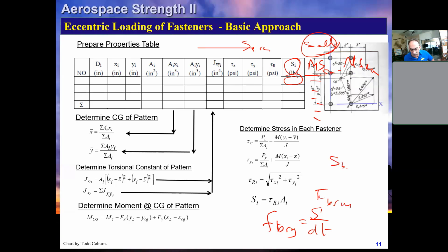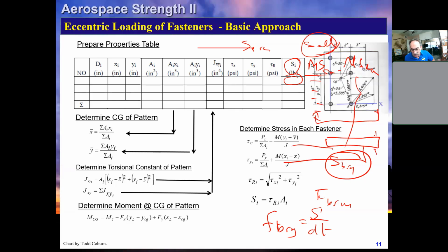If we have an S bearing of the fastener, then we can just write the margin of safety directly. If we need to calculate bolt bending, we look at the cross section of this plate, and we can see we have this plate and it's bolted to something else. We would need to know what the thickness of each plate is. And now we'd calculate our eccentricity, right? It's just that shear times the eccentricities of the moment. And we could calculate our bending of the bolt itself.